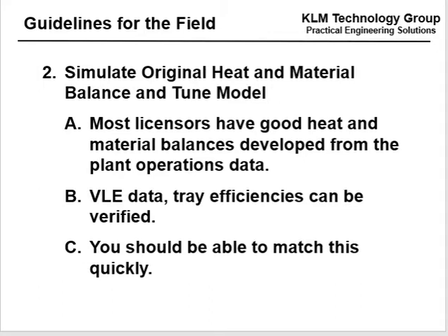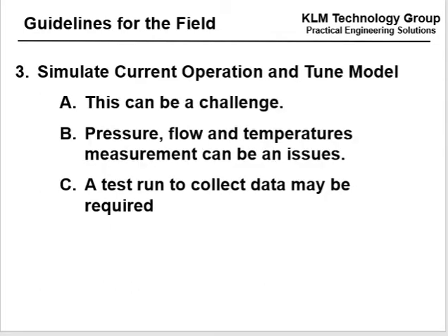Simulate the original heat and material balances. Most licensors have a good heat and material balance developed from plant operations data. VLE data, tray efficiencies can be verified. You should be able to quickly match the original heat and material balance in your simulation.